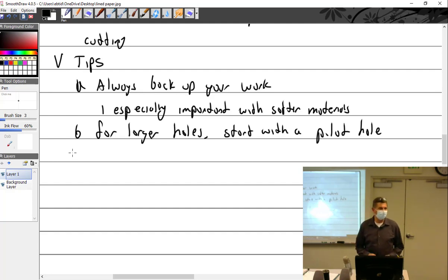But if I want precision, like just say I'm doing aluminum, you can take a 1/2 inch and punch a hole through aluminum. It's not that big of a deal, especially if you have a drill press. Just get down on it, it'll go. But for precision, I like to drill a number 30 first, or 40 maybe, and get that hole perfectly lined up and started, and then drill it through, and then go to something that'll follow it. So it's just more precision.